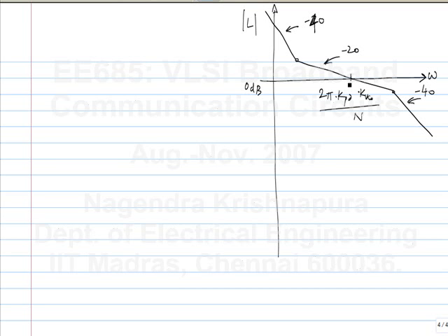This is one of the reasons. So L over 1 plus L will be this. Okay. It also tells you that any poles in the loop gain that you have beyond the unity gain frequency will appear just like that in the closed loop transfer function also.